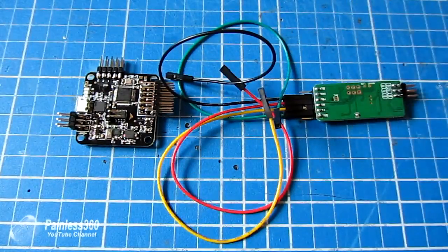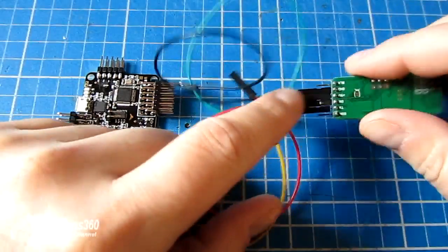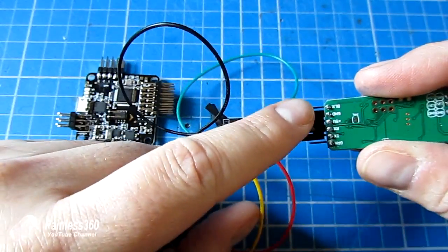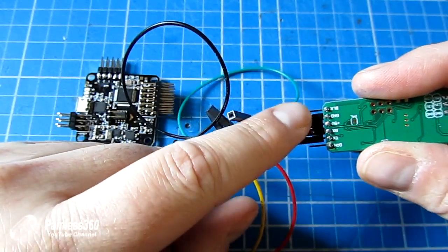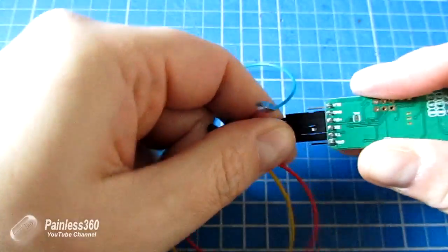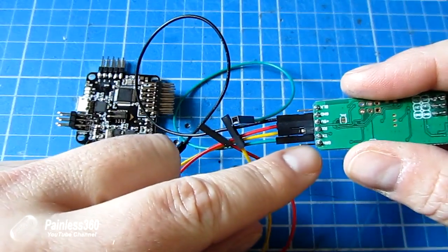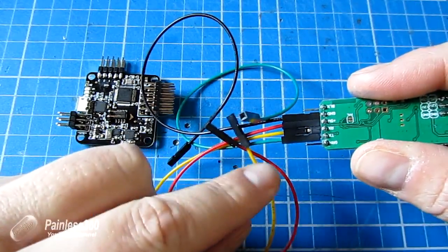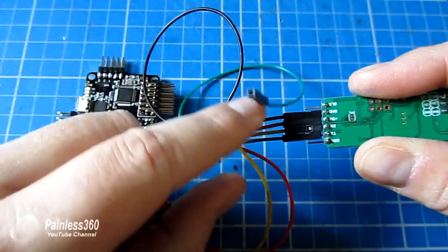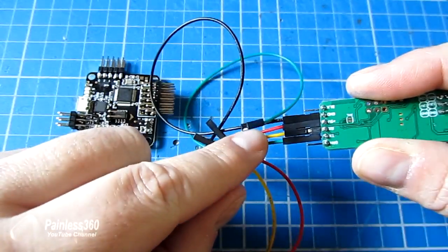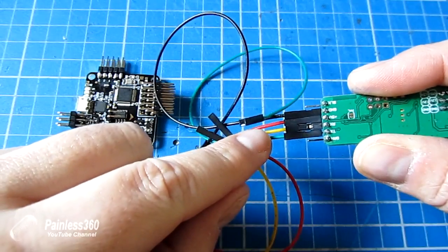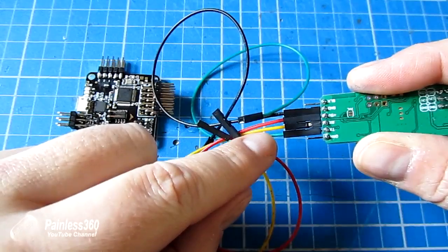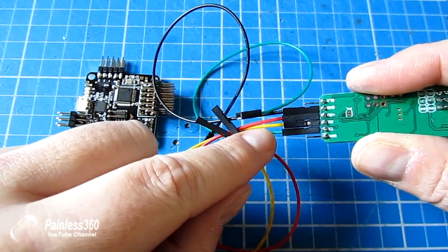So here we have it ready to do it in real life. I've taken the liberty of actually plugging in each of the cables on the MinimOSD. Underneath it very clearly labels which pin is which, but yours isn't. From the green end it goes transmit, receive, plus 5 volts, ground and black. I have the black cable plugged into ground, the red cable plugged into plus 5 volts, that's just convention, it makes it easier. The yellow cable is plugged into receive, and the green cable is plugged into transmit.